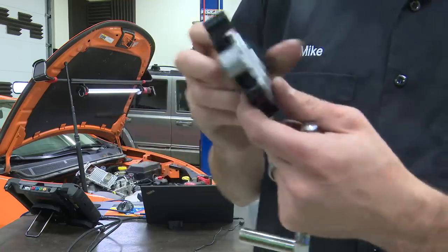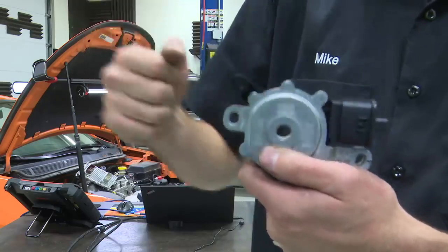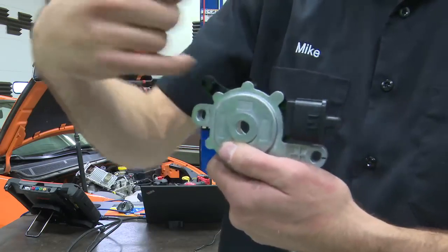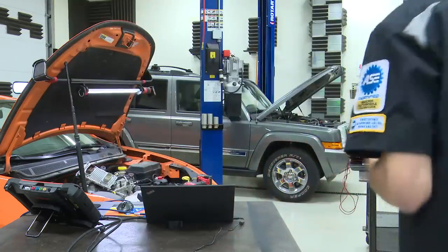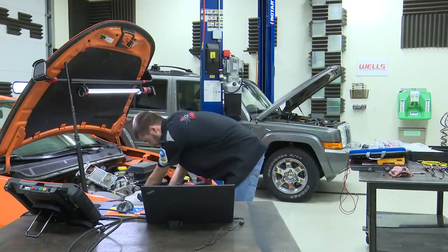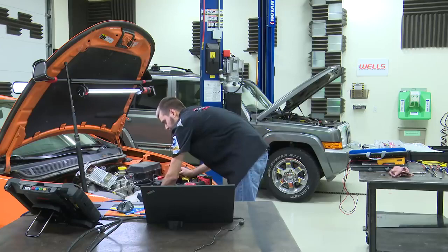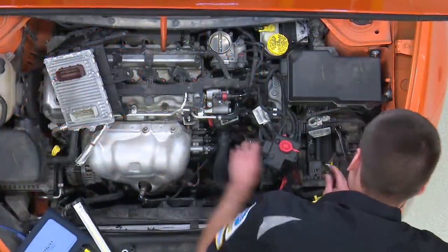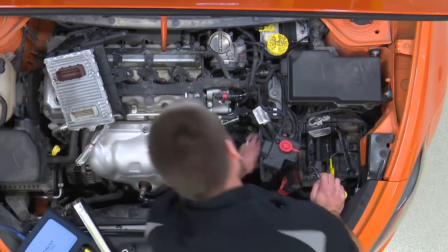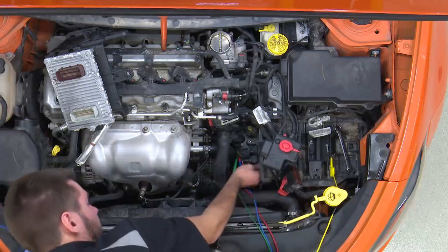When we install this switch, this hole here is going to line up with our part of our shift cable, or our shift shaft, our shift cable. You're going to put a pin through there between the cable and the new switch. That will be done in neutral, and that's how you adjust it. So it should be just a matter of pulling these 2 10mm bolts out. And pulling our shift shaft off the top of the shaft in the transmission.